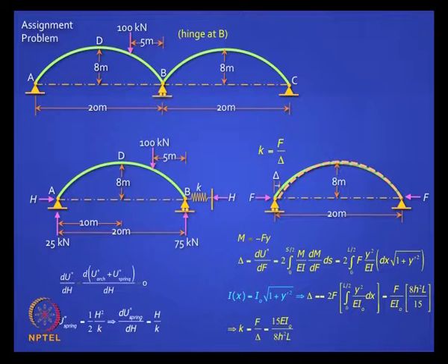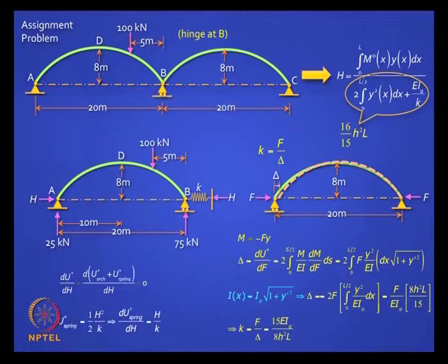K you already know, so you can now use this concept and get an expression for h. So go back to the original theory, you will find when there was no spring this term, EI naught by k, was not there, that is k was infinity, right. I want you to derive it from first principles, you will find you can do this, and you know the denominator, you can add up this value of k here with the value that we have derived for the parabolic arch. Now it is easy to do, right.